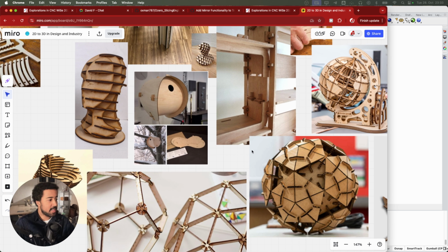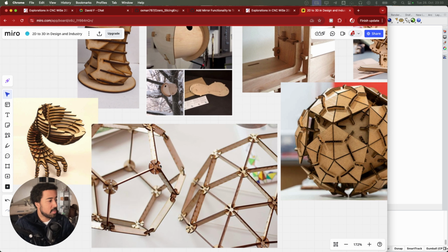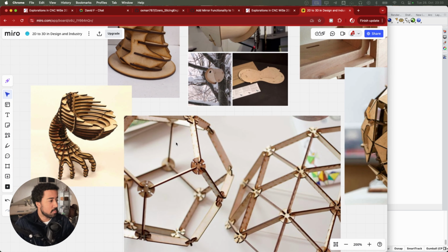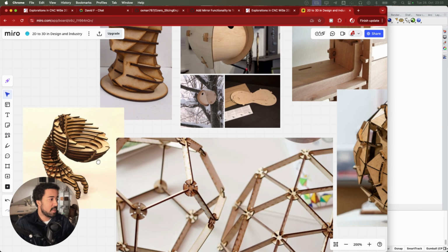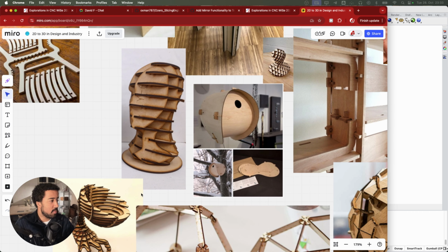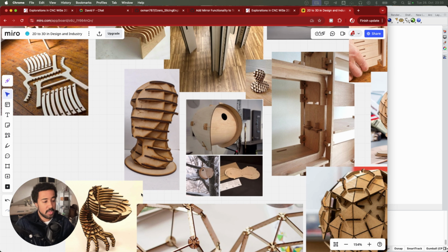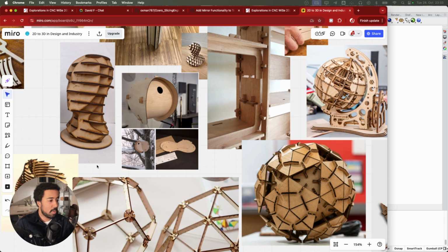your project. And we then cut slots into this material in such a way that we can assemble three-dimensional structures from it. So we have very simple material that can be cut very easily in a two-dimensional process, and then we can assemble quite complex 3D geometry from it. And depending on the material you want to use, you might want to use different parameters and different kinds of slots, but Grasshopper gives us a very simple way of creating simple slots that I want to show you in this tutorial. And of course, you can go on and explore more sophisticated ways of creating these slots.